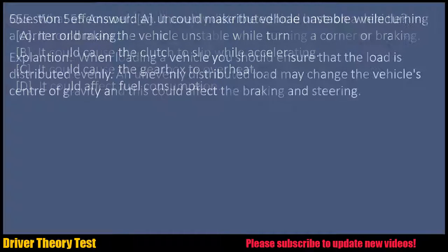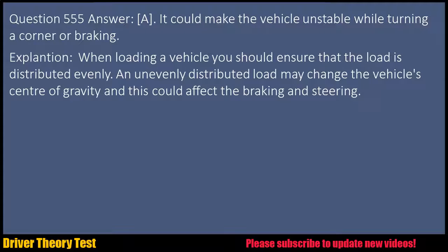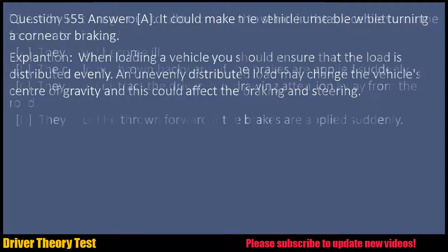consumption. Question 555. Answer: A. It could make the vehicle unstable while turning a corner or braking. Explanation: when loading a vehicle, you should ensure that the load is distributed evenly. An unevenly distributed load may change the vehicle's center of gravity, and this could affect the braking and steering.